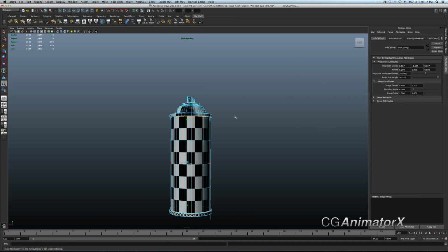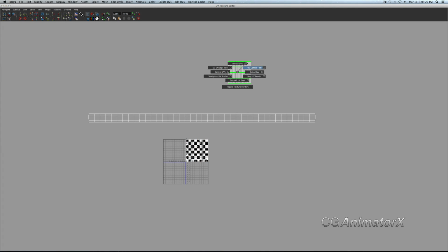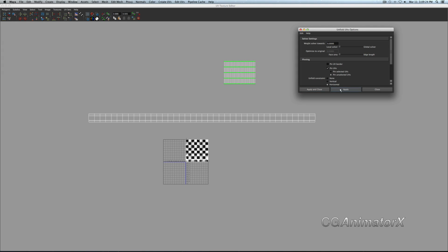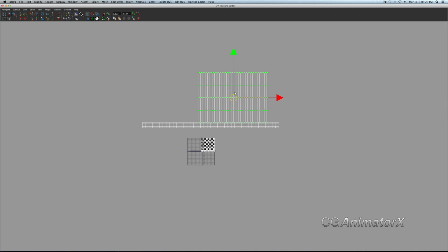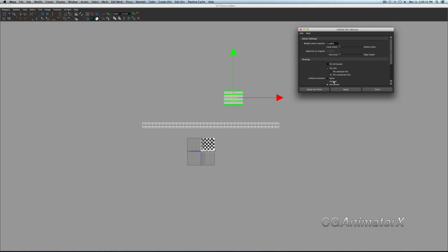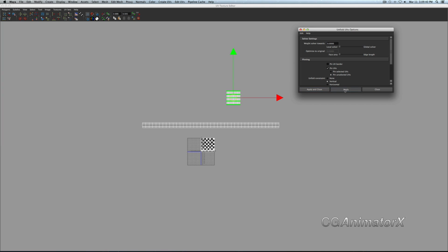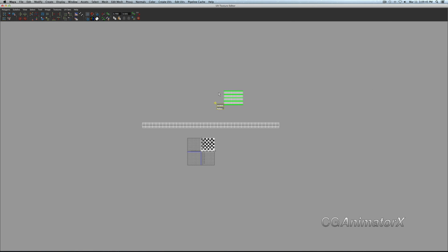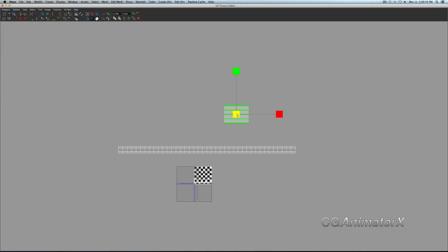Cylindrical mapping, project, do a 360. Select this shell, unfold UVs, horizontal, and there you go. And then let's see, or I might do that again, because I might actually go from a vertical first. Nope. All right. That seems to have done the trick, I hope.